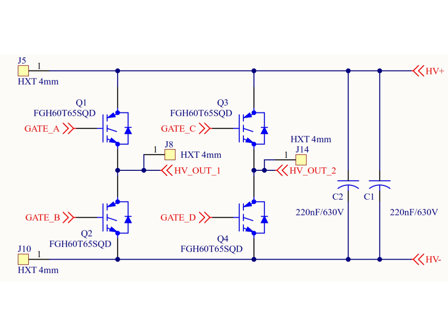When we combine both conduction and switching losses, the total power loss of the H-bridge remains under roughly 100 to 150 watts, allowing the inverter to achieve efficiencies well above 95%, which is excellent for this power level.